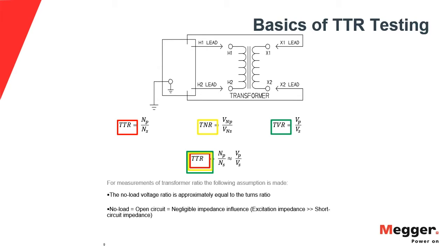We're obviously discussing the simplest two winding transformer case. So with that, I can also do a relationship and get what is called transformer nameplate ratio. If I take the primary voltage divided by the secondary voltage rating, then I get my transformer nameplate ratio, my TNR, which is highlighted in yellow.